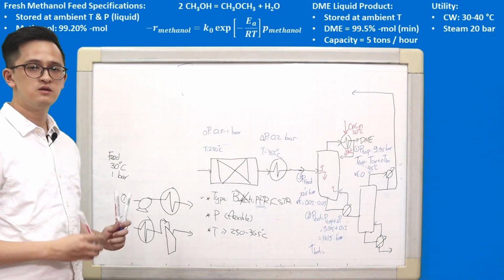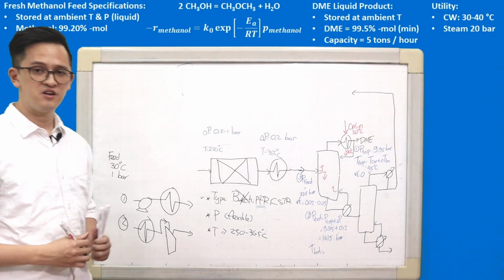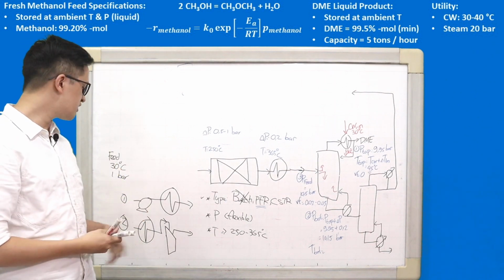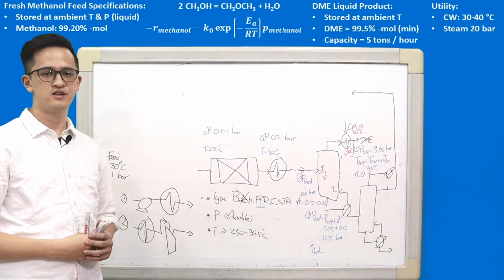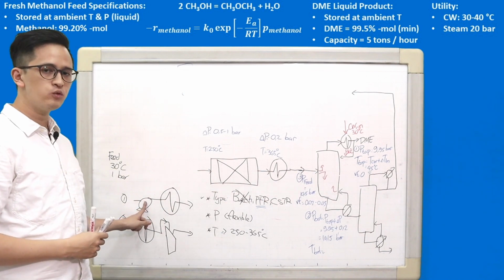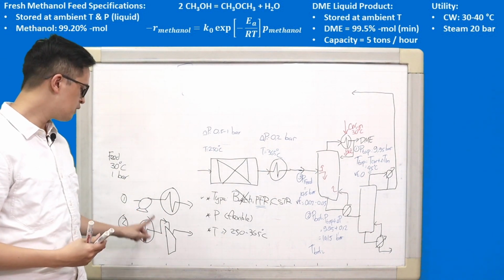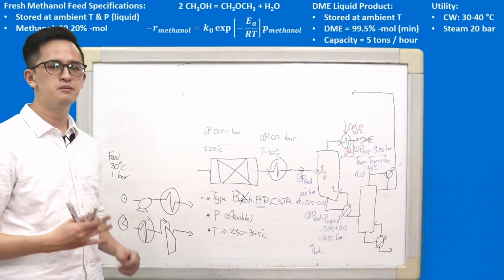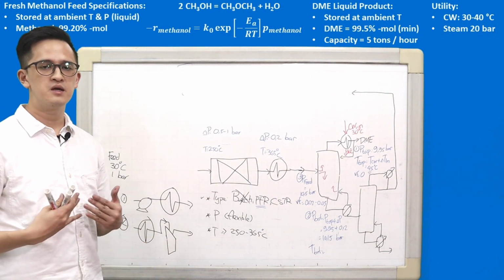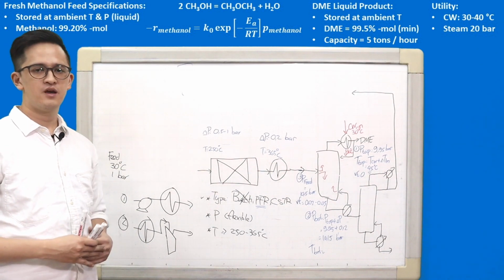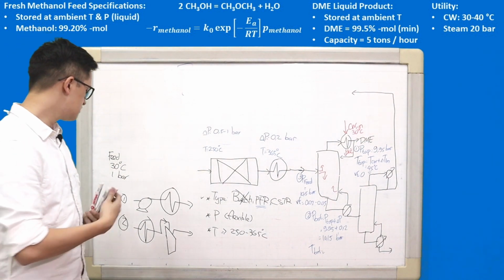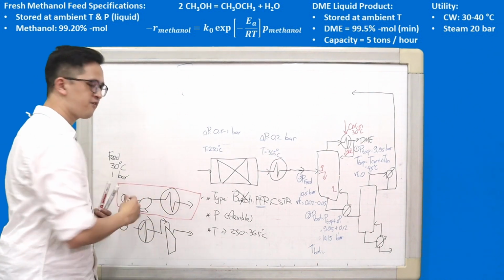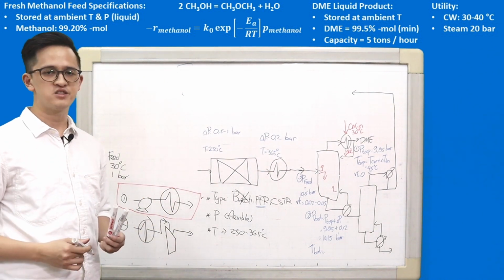For this one, you have to remember again the thermodynamics and the fluid mechanics course. Okay, what's the main difference between a pump and a compressor? One is dealing with a liquid, which is an incompressible fluid. One is dealing with a vapor, which is a compressible fluid. Which one would be more energy efficient, which would be cheaper to perform? Actually, the answer is that this option will always be cheaper at the same capacity and the same pressure ratio.